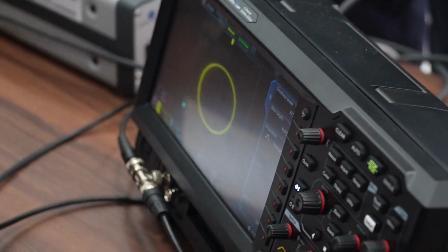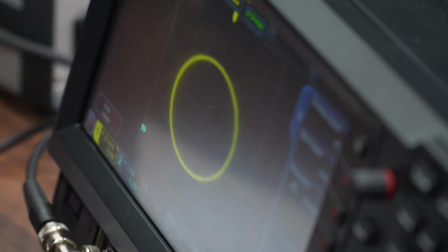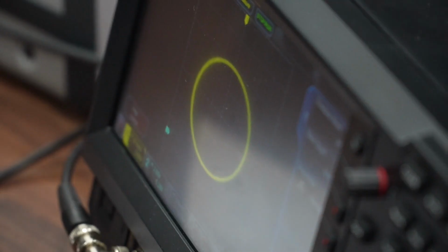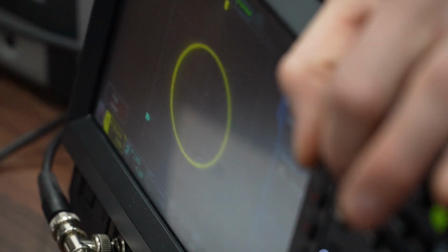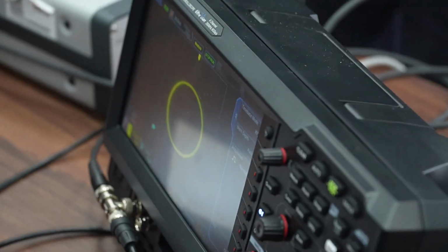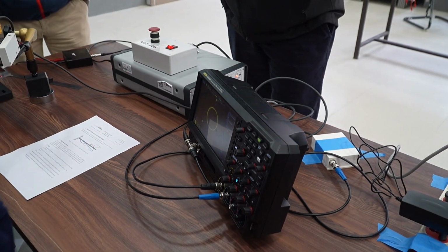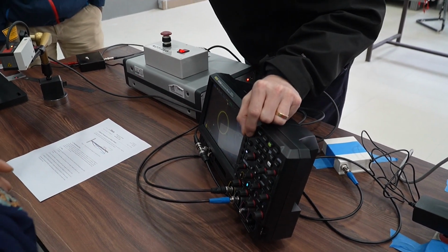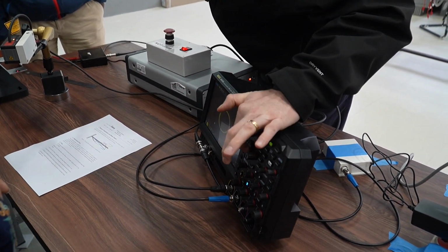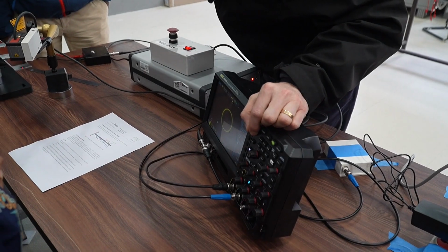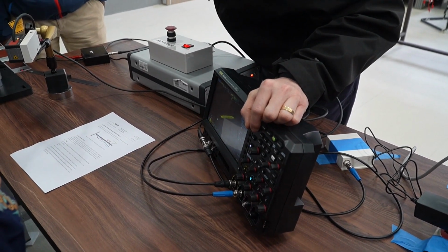If you're in the eigenfrequency and you plot the one signal over the other signal, so the excitation over the amplitude, what you will see is a circle. It's called Lissajous figures, after the man who first saw these figures. Now I will again increase frequency just a little bit and look at the circle.